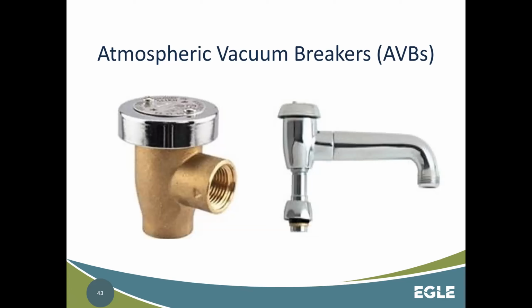Atmospheric vacuum breakers. Okay, so atmospheric vacuum breakers are non-testable. As you can see, this is our first quote unquote device. And the reason this is our device is, look, you don't see any test ports off this thing. These typically are found in two places. They're found in slop sinks or lab sinks, and hose bibs on the outside of houses is typically where you see these. They can't be used in commercial dishwashers or sinks. I've seen them in those areas too. They can be, but a lot of times they're not. And there's a reason for that.